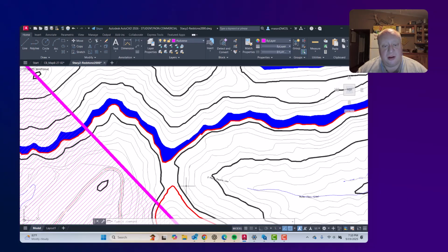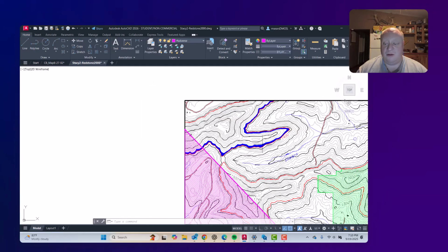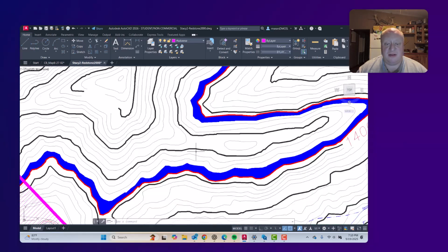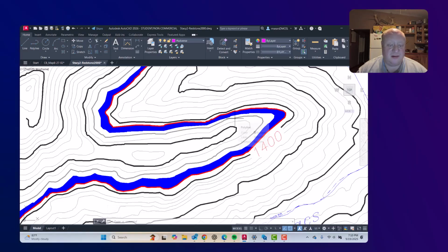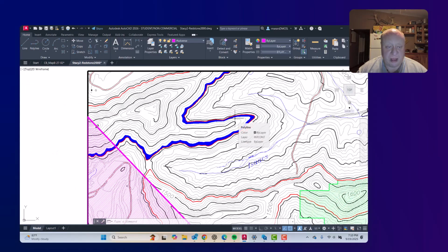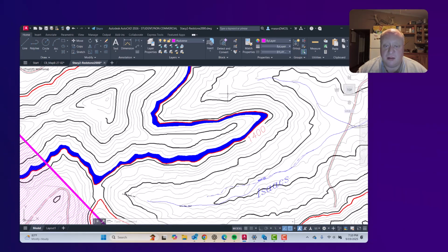Maybe store it here, depending on volume. Maybe you need to start a small valley fill and have that permitted. There's other options. Okay, here for example, you could shoot this point off, but then you have to decide there's going to be somewhere you got to put this before you start hauling back onto the same site using the haulback method that I'll talk about in a minute. But you could shoot this off here, maybe put in a small valley fill here, or bring it back around and place it here so that you can get started.